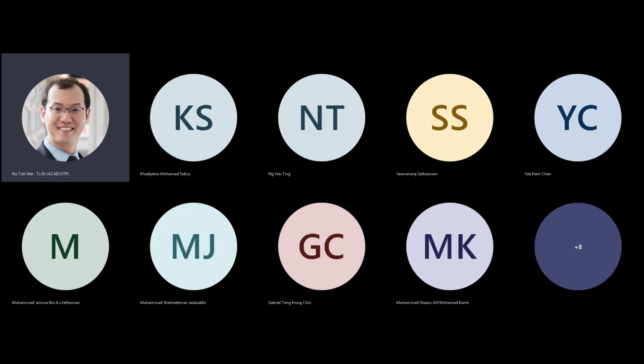So where we'll be going with this, remember we had our switch network model of the logic gates. Okay. And this switch network you can actually draw like a chain of transistors, NMOS, PMOS, CMOS gates, a chain to mimic this, and then these transistors will be approximated by resistances and capacitances, and we'll be looking at evaluating the RC time constant, the effective RC time constant for all these to change state, right?